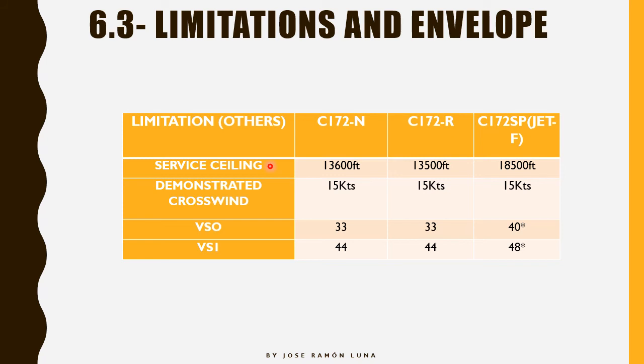Cessna tells us that the service ceiling for the Cessna 172 November is going to be 13,600 feet. You're lacking just a little bit of oxygen there. It's not too bad, but I wouldn't suggest being there for a longer time. As you guys know, above 10,000 feet it starts to be the non-safe area for flying due to the lack of pressure in the air to push oxygen inside your body.